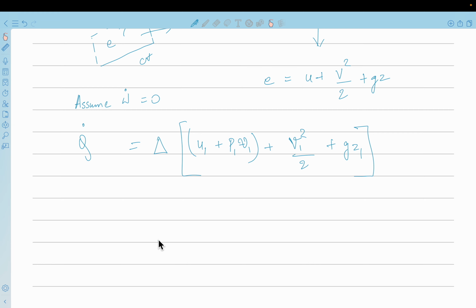Okay, so from the energy equation, after doing a lot of rearranging, you can see there are these terms, the pressure term is there, the velocity term is there. You can further derive that P by rho plus V square by 2 plus gz is a constant.